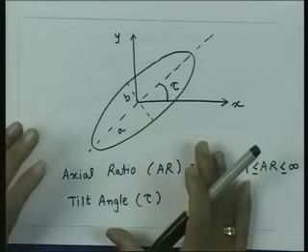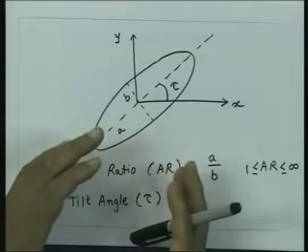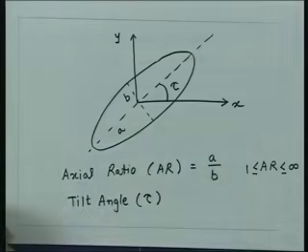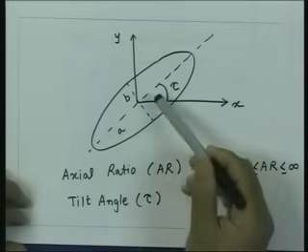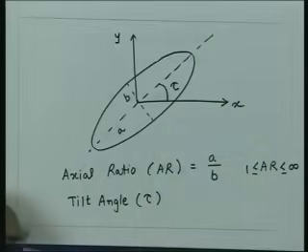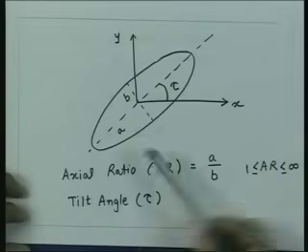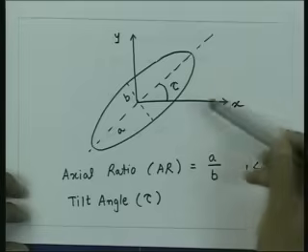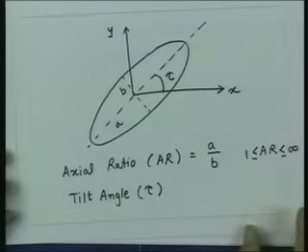There is no mechanism here to define the way the ellipse was drawn. So, to put that information of where the ellipse is drawn into these parameters, we assign a sign to the axial ratio and follow a convention that if this sign is positive, then there is one sense of rotation. If the sign is negative, there is another sense of rotation.